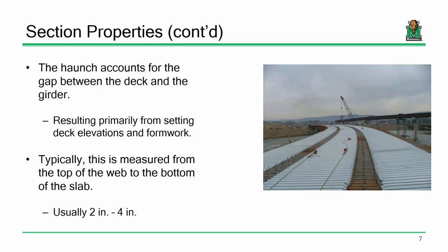elements like shear studs and connections and what have you, and those fabrication details, they can experience failure at really, really low stresses. To give you somewhat of an analogy, have you ever taken a paper clip and bent it back and forth a few times and then it kind of just gets softer in your hand and it kind of snaps? You know what I'm talking about? That's what's called low cycle fatigue, because you do it only a few times and the paper clip fails. What we're doing is we're not applying those very high stresses, but we're doing it millions of times.